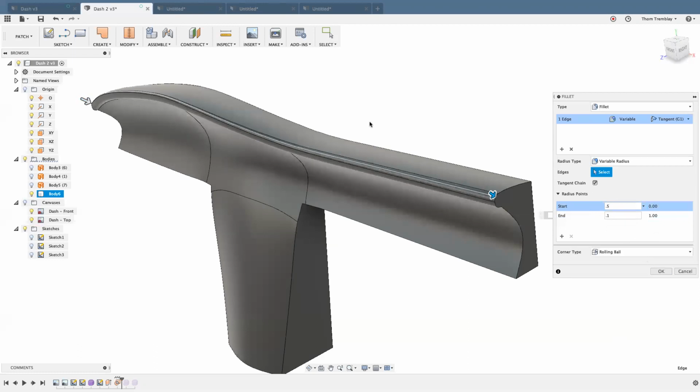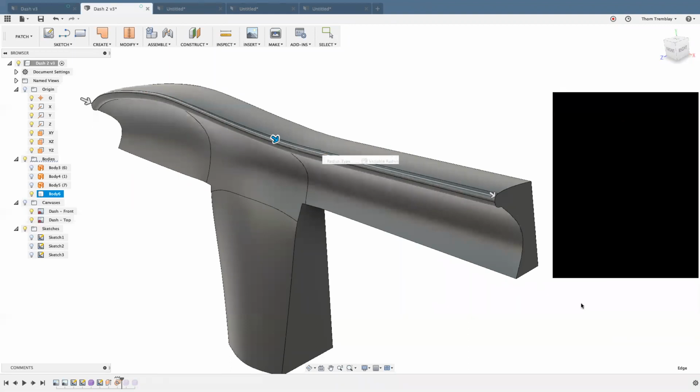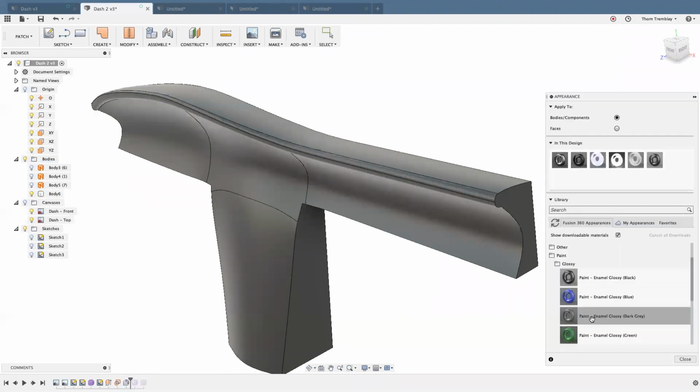There. And then I can always, in the middle somewhere, pick another point and change not only where the position will be, but change what that radius will be at that point. So I can say 0.4 from there. Set the radius to 0.4 at 0.4 of the length. So you can control how that transitions. Again, let's give it something a little more interesting.